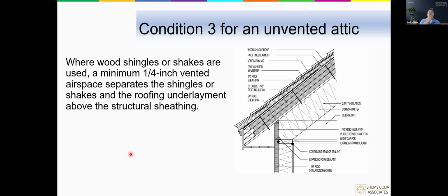like my neighbor." And this is a place as a code official and as an installer or a builder that you want to be really, really specific on to know the code and to know what the parameters are where you might not be able to provide that service because these roofs actually do need that breathing capacity that might be eliminated from them based on certain insulation criteria if they don't have some sort of gap or substrate in there that's going to allow for a little bit of a cavity for airflow. So here we see what's used is called a ventilation mat. It's a specific product meeting that criteria to add that 1/4 inch of vented insulation.